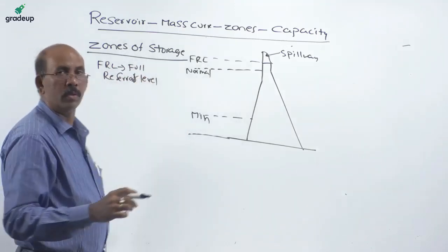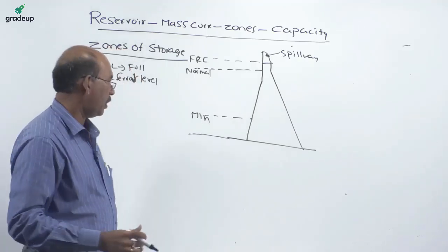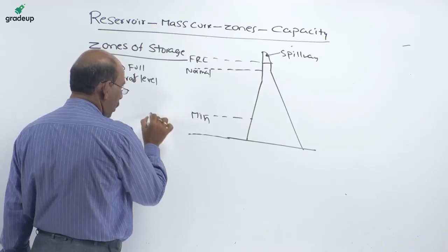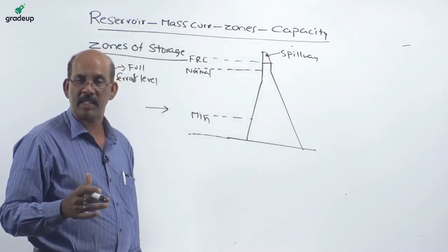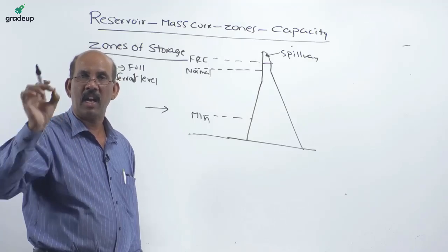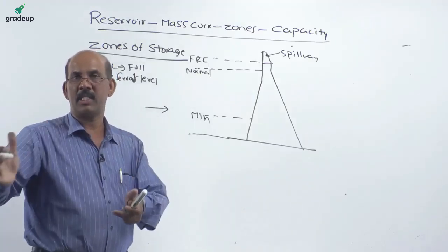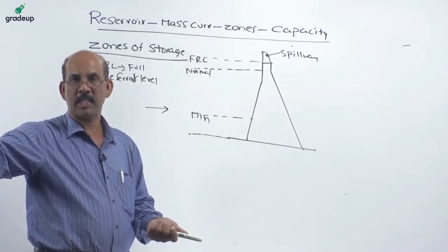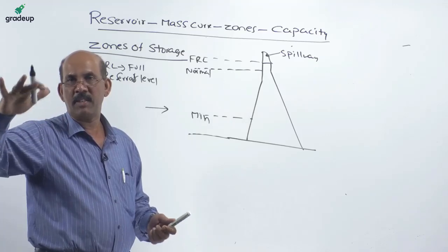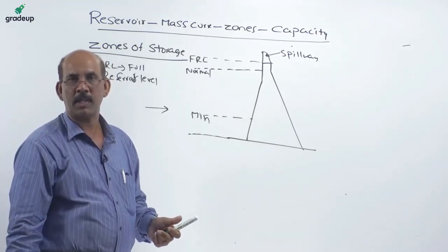These levels are very important. The minimum level: as the flow during the floods carries a lot of sediment particles, once the particles enter into the dam, the kinetic energy is converted to pressure energy and the velocity decreases, so particles cannot move and they settle down.